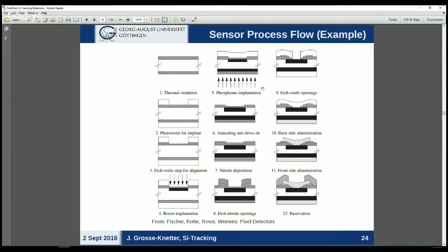So you can do the same to the opposite side of the wafer, which doesn't necessarily need segmentation, just for the contact. Then you add some metal on top in order to allow easy electrical contacts, and that would be the rest of the picture. Skip that. So that's the core part, how to create pixels in your silicon.